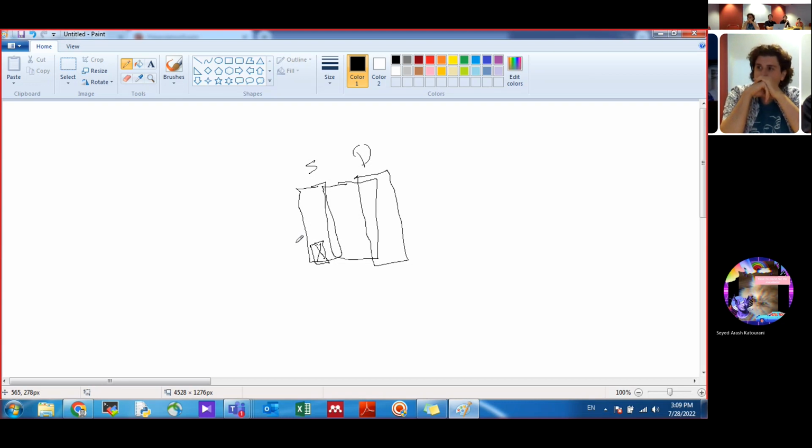So this is a very good comment. We should always use lots of vias because of the RC and everything. But it also depends on the space you have. For example, if you have a multi-finger transistor, you have to connect the source and the drain, so we use half of the space. But it depends on the current, on whether this transistor is just an inverter or, for example, a big LDO, a fast transistor for an LDO.